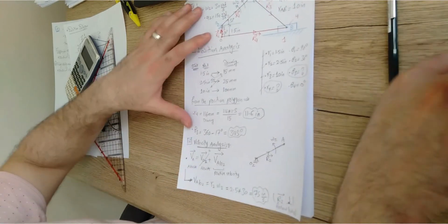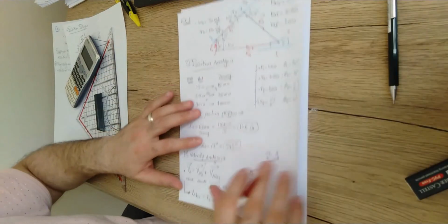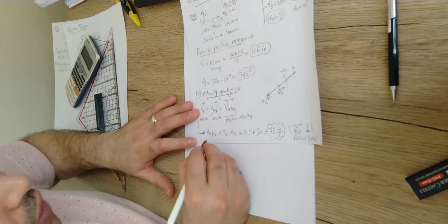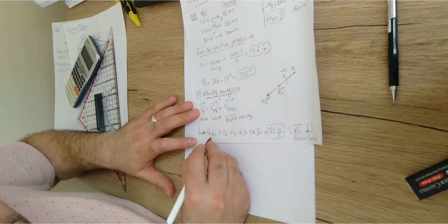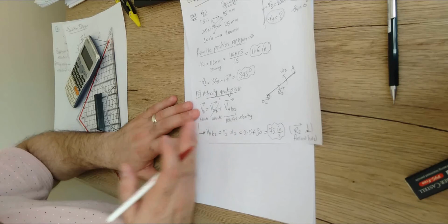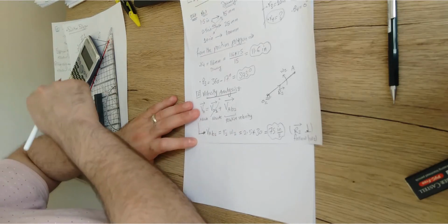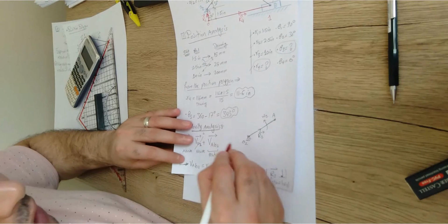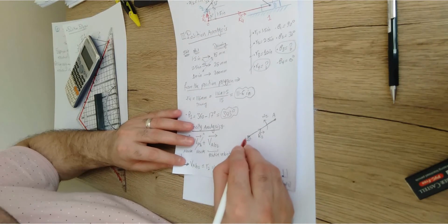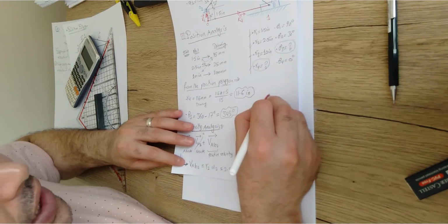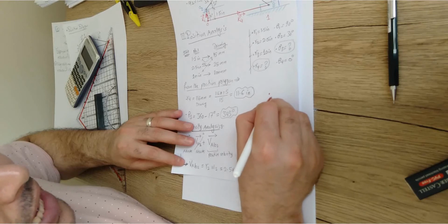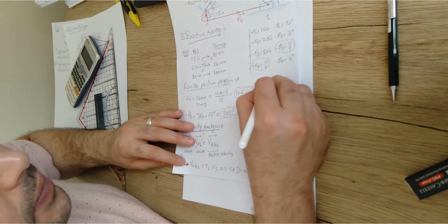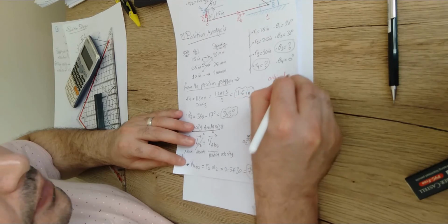But another point that you should understand about this relative velocity, VA relative to O2, is that it should be drawn from either point A or point O2, depending on which point is already located in the velocity diagram. Generally speaking, any point like point O2 that has zero velocity should be considered a point that we're going to name OV. What is OV? This is the origin of the velocity polygon.